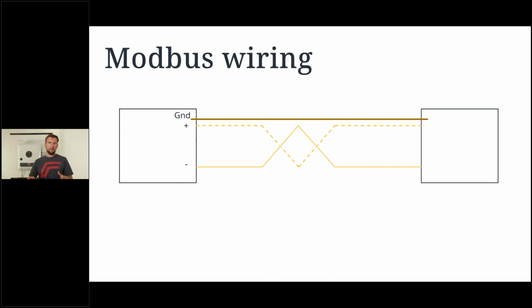Between the plus and minus at the ends of our line, we're also going to have to make sure that the signals don't cross over. And to do that, at the end, we're going to put in a termination resistance. Now, in our case, this is going to be 120 ohm termination resistance between plus and minus at the end of every Modbus line. What that termination resistance does is it swallows stray signals, any signals that are excessive, so usually interference, so it does not get transferred from a plus onto a minus signal or misinterpreted at the other end.